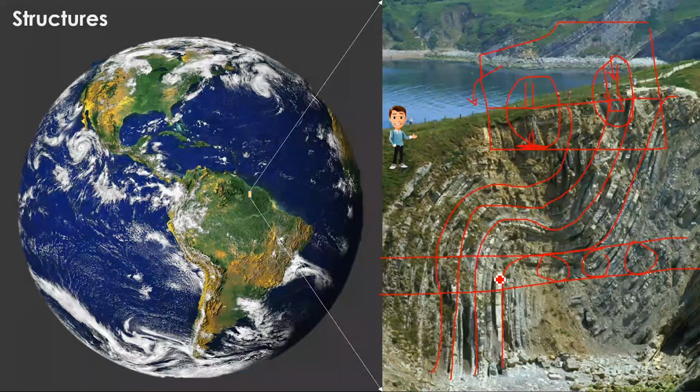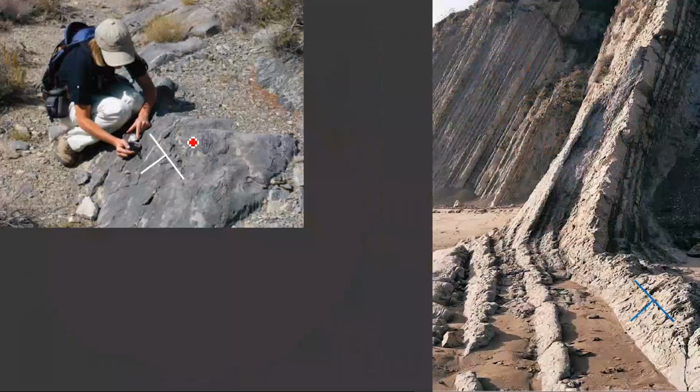But how do we know these characteristics? We know them by understanding the exposed strata. When I get a strata which is exposed on the surface, I measure some parameters on the surface. Then I understand that this strata is not horizontal, it is slightly inclined. Like here, if you see the character of this rock which is exposed, this rock is inclined in nature. This indicates that the rock in this region is not horizontal, rather it is inclined.